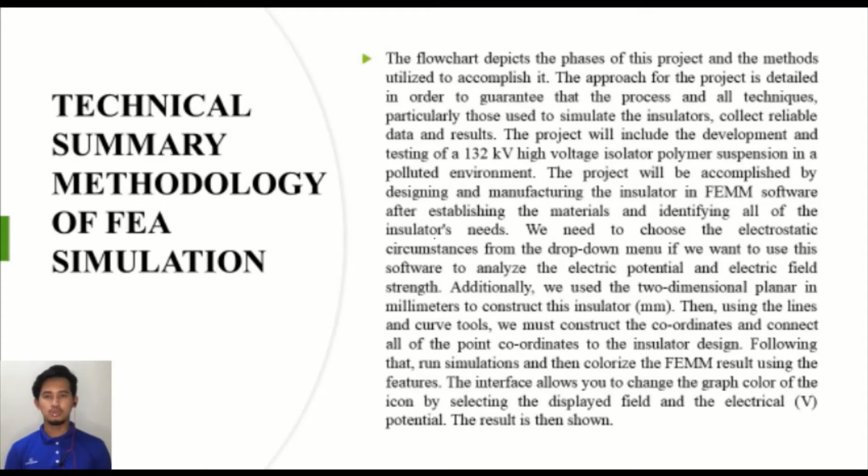We need to choose the electrostatic circumstances from the drop-down menu if we want to use this software to analyze the electric potential and electric field strength. Additionally, we use the 2-dimensional planar in millimeters to construct this insulator.